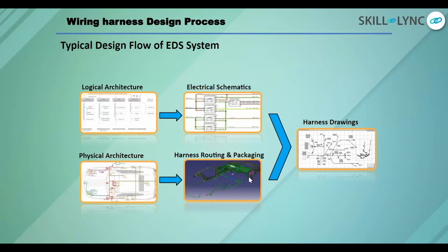So now after a design engineer develops these, his aim is basically to develop a harness drawing. It's just like any design engineer who works on developing drawings. His part will be to make sure that he develops a drawing for your harness. Okay, so out of the 3D data, whatever he is having, he is actually going to develop a 2D model. This 2D model is going to have data like what set of wires is being utilized, what wire standards are being utilized, what is the length of wire, and what the other components are which are going to be a part of those wiring harness components.